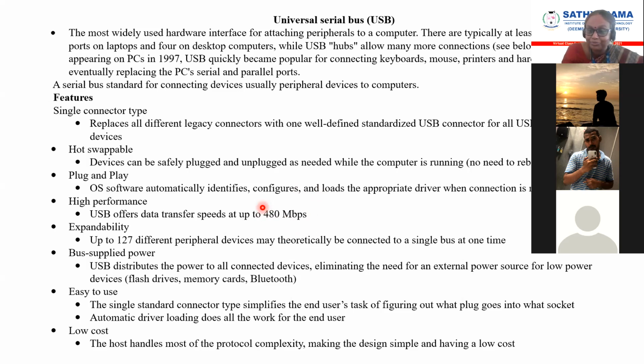Yeah, Harshavardhan. 20 kilobit per second. RS232 can transfer 20 kilobit per second, and RS485 can transfer 100 kilobit per second. While we are discussing SPI and I squared C, it will transfer several megabit per second or kilobit per second. But you see, USB has the highest speed. Now I have disconnected and connected. It is easy to plug and play, and the speed is also around 480 megabit per second. So that is mainly the advantage.